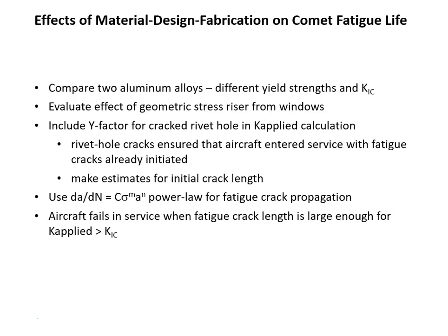You can literally virtually redesign your de Havilland using different Y factors for rivets and predict how it could have been designed better using our understanding of K1C and a fatigue crack propagation formula using a power law of real data for real materials. So that is certainly an exercise we can step through, again, not during this lecture, but it's an interesting way to use already existing knowledge of our materials and look at how that could have been done better.